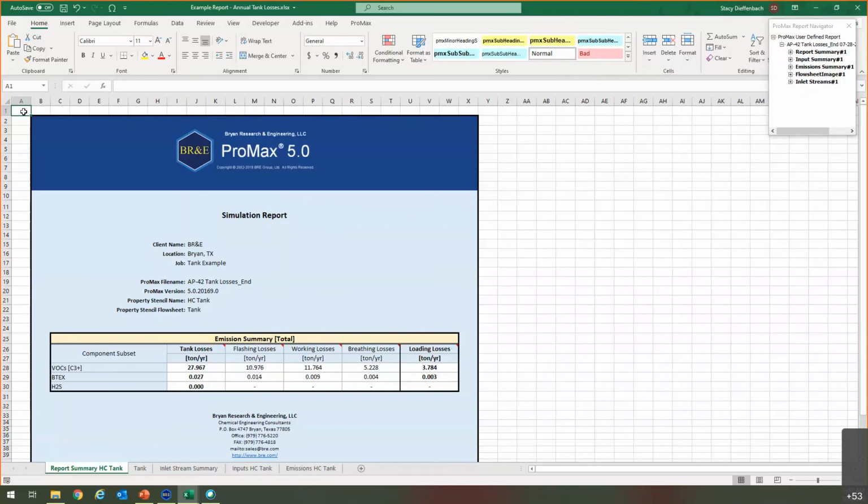It's not exactly the same because it's bulk temperature versus liquid surface temperature. But especially for fixed roof, it's really just one equation. You can pull the numbers you need out of ProMax and then do that equation, because you can find very easily in a stream what the vapor pressure at 95 degrees would be. And you can plug that in, since it's really just one equation with a few inputs.